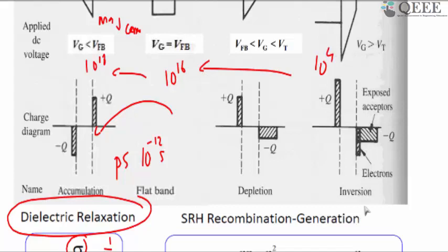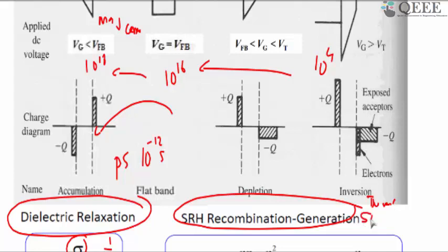It comes from something known as trap levels. Inside the material there are always trap levels. So one is thermal generation, and suppose there are traps. You might have studied something known as the Shockley-Read-Hall method. This is inside the band gap, so this is Ei here. There may be additional levels here, trap levels, which are closer to the Ei.